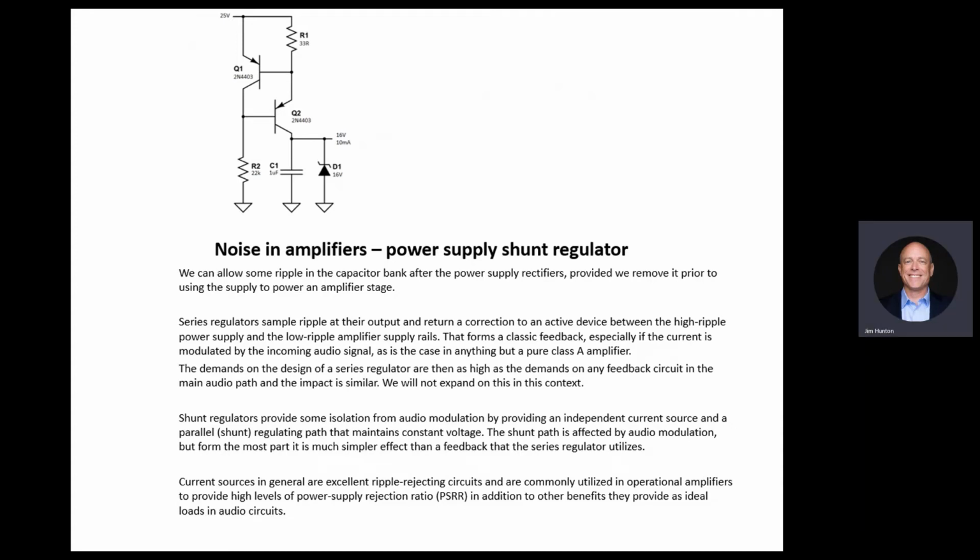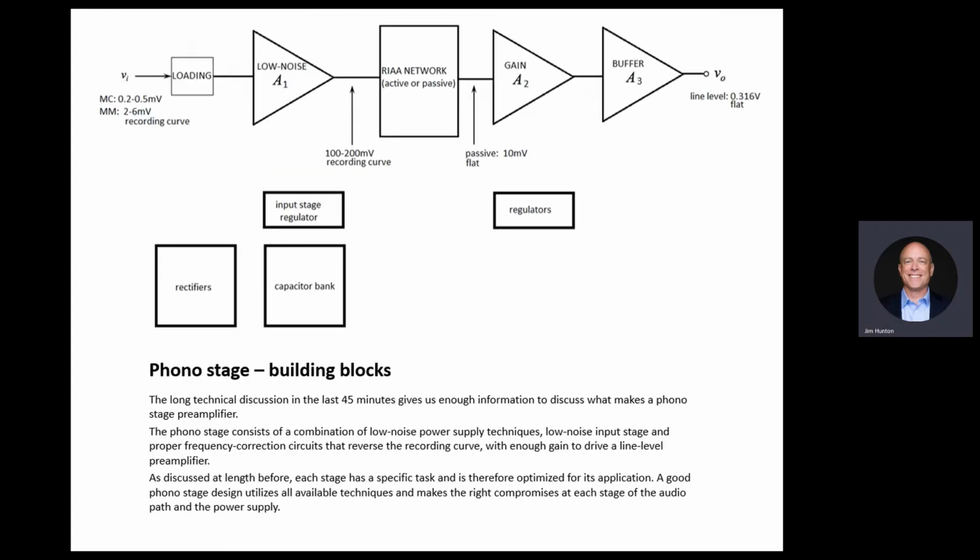Do you sacrifice current? If you're building a power amplifier with hundreds of watts, no. Shunt is not a good idea, at least not on the output stages. If you're building preamps, phono stages, sure. And when you sacrifice half a watt, you get a much cleaner supply that's independent of the audio. So shunt regulators all the way.